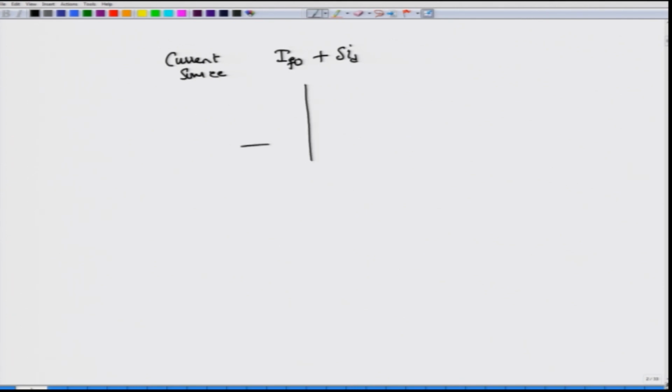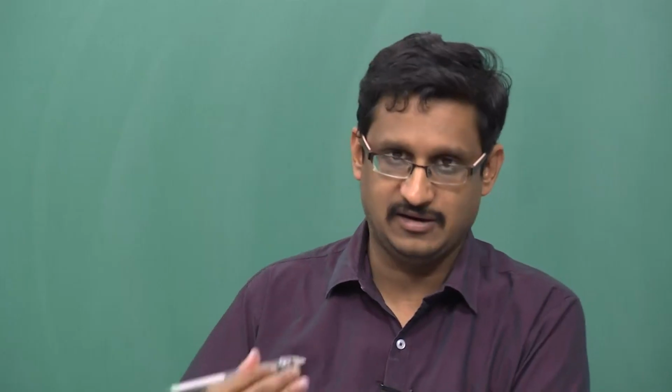So, if you look at how the forward current versus the light output, which is usually denoted by L, and L stands for luminosity, but in our case we can equally think of this as the power coming out from the laser diode. You would see that this follows more or less this characteristic. As the forward bias increases, the power increases. There is a certain threshold value that is necessary for the laser to begin acting like a laser itself.